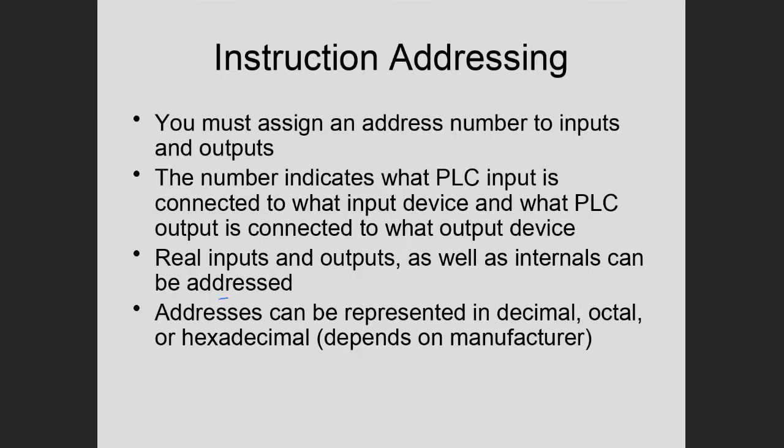It talks about how some addresses are written in hex, some are written in octal. I think yours are in decimal. You are familiar now with all those number systems, so that shouldn't faze you. The particular simulation software you have is made to mimic the Allen Bradley SLC 500 PLC, and they use decimal numbers for the bit positions 0 through 15, which makes it convenient.